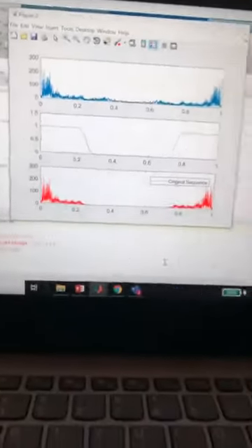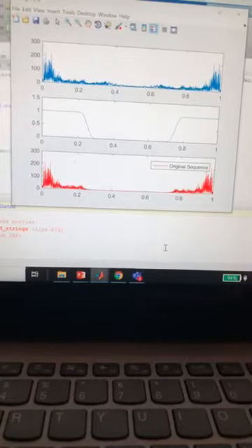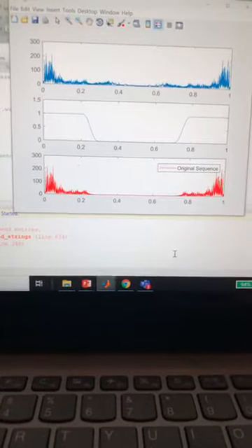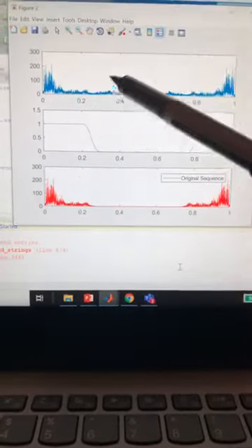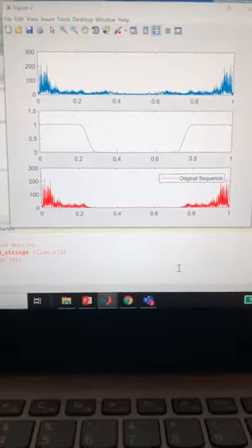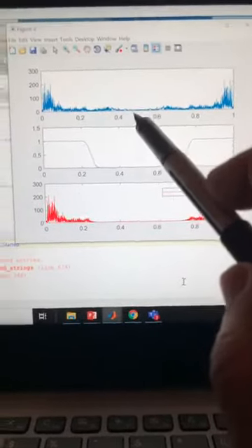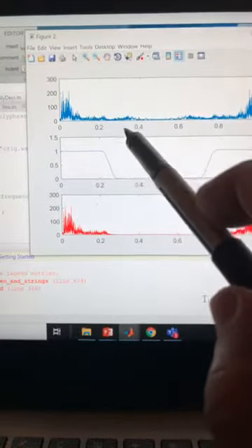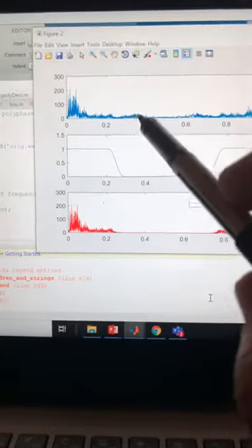So this is an important plot. This is the spectrum of the voice, okay? And as you can see, the voice usually has this type of a spectrum where most of the energy is in these frequencies. So this is sampled at around 11 kilohertz, so about 5.5 kilohertz is the pi frequency. So you see the frequency contents in this part of the spectrum, very low energy.